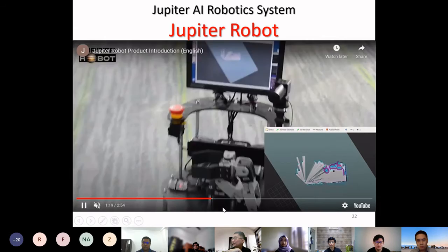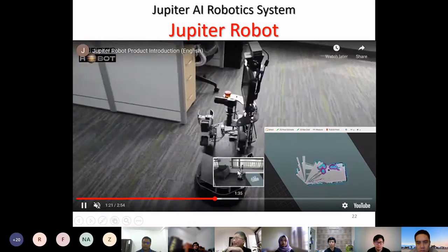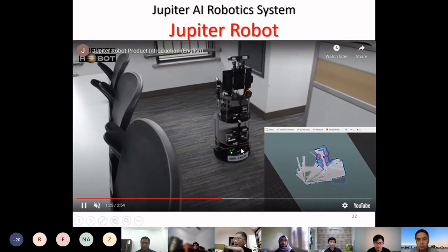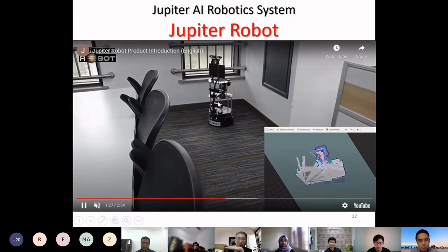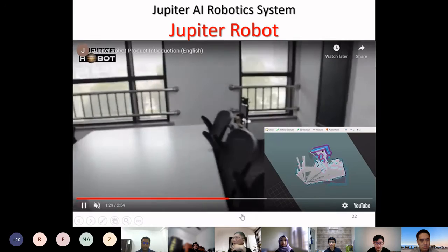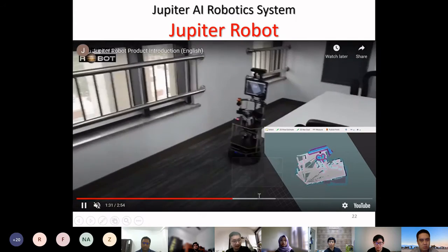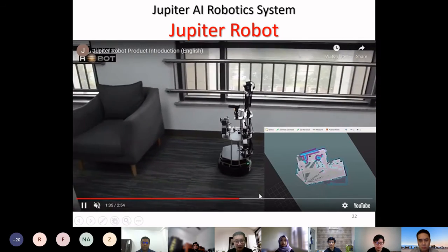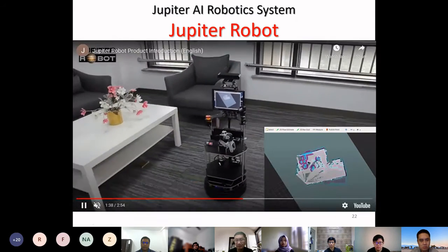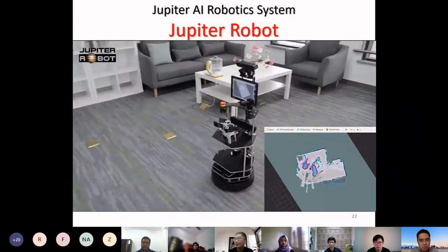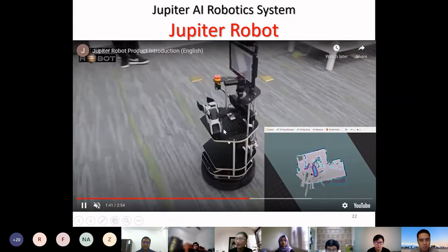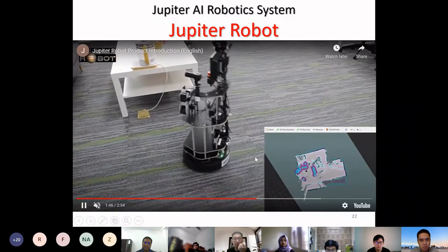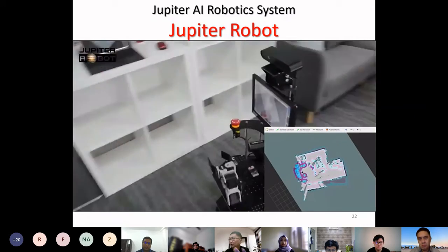And you can see we actually have two kinds of sensors for the navigation. We can use the RGBD, or we have another version which uses the laser, which I think you have one from your Turtlebot 3, the RP LiDAR A1. So we actually have that version as well that we can mount underneath the top plate, and our example actually uses that to show you how to make a better map and so on.